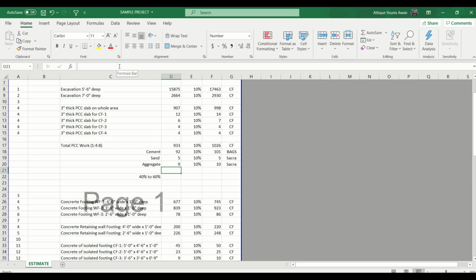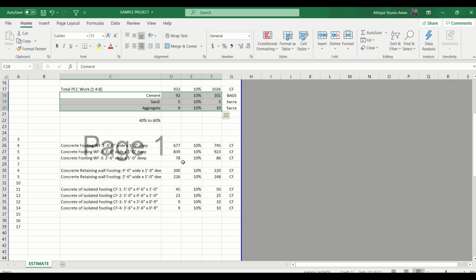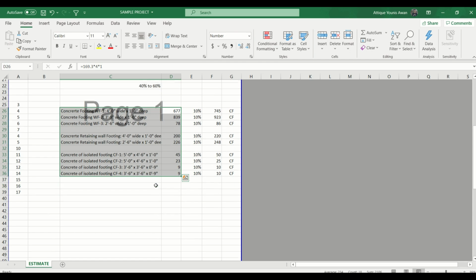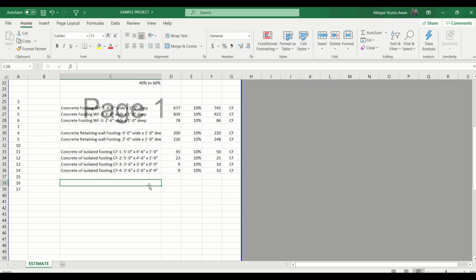So this is the level of detail which I was discussing in our previous session, that is how we are going to calculate these small units of estimation. So if I go ahead and calculate the constituents of this concrete work except rebars, which I'm going to discuss in the next session, I'm going to repeat the same process to get the total concrete work.